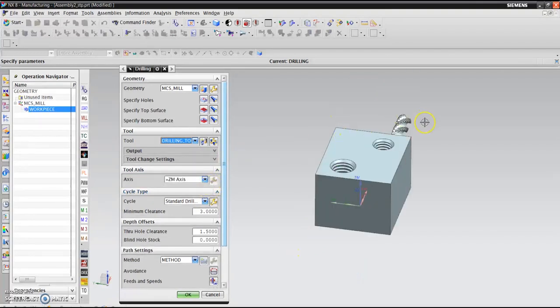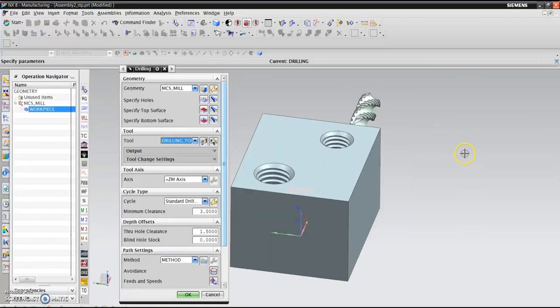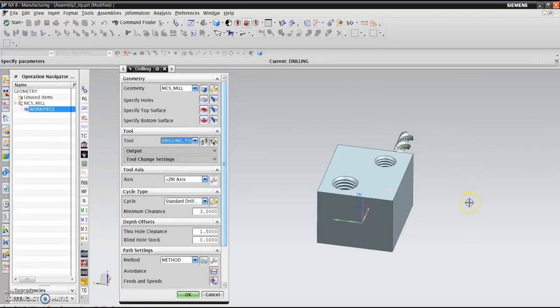So canned cycles, most people who use the CNC will know about the canned cycle, G81 cycle, G83 cycle. If the machine has excellent through coolant capacity with a good pressure, coolant coming out, and you have a through coolant drill, even with a 6 or 7 length by diameter ratio, you can use a single shot G81 cycle.